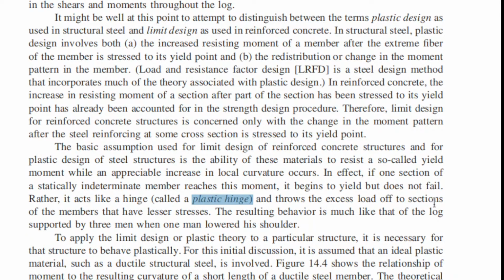Rather, it acts like a hinge and throws the excess load to sections of the member that have lesser stresses. So this is what we mean by redistribution of load. The resulting behavior is much like that of a log supported by three men when one man lowered his shoulder.